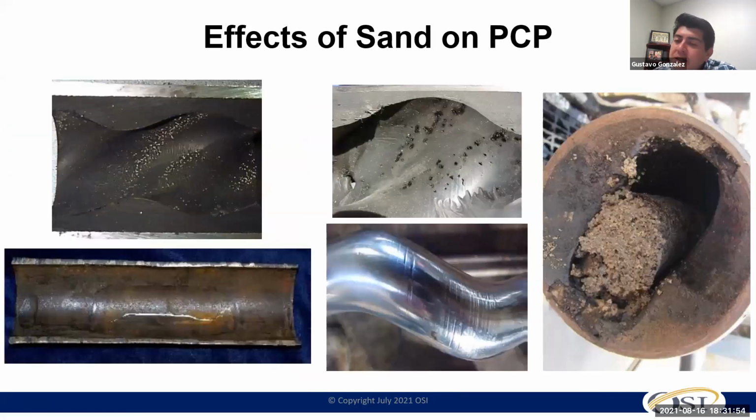In some areas we use PCPs, either after the second installation, after the first installation, or in the first installation. And you know, PCPs are normally designed to handle sand, and they do an amazing job. You can actually lift 30 to 40% more sand compared with a rod pump. But it gets to the point that the volume is too high and too severe, and the damage I'm causing to my stator and to my elastomer is going to be severe.